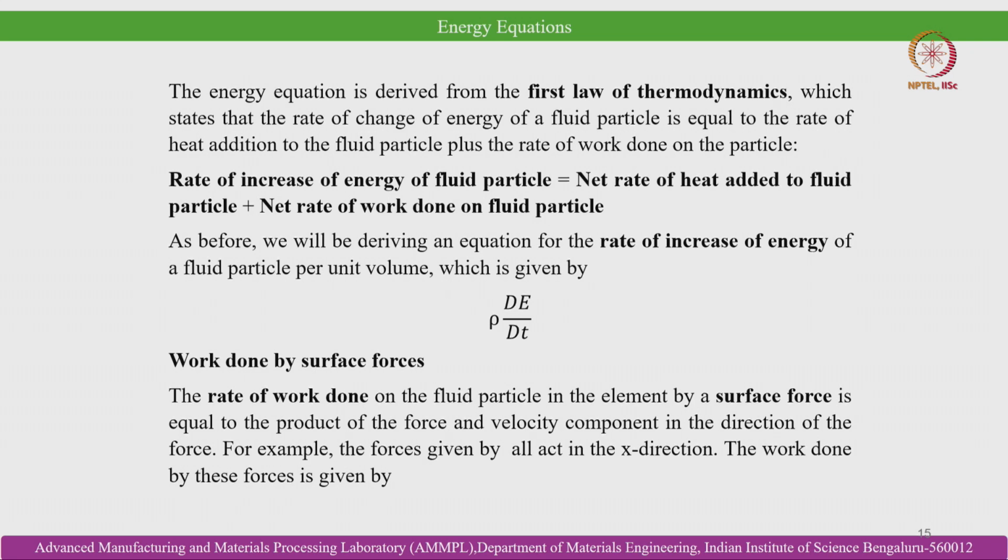As before, we will be deriving an equation for the rate of increase of energy of a fluid particle per unit volume, which is given by rho D/Dt, that is, rho times the substantial derivative of energy. Then, work done by surface forces. The rate of work done on the fluid particle in the element by a surface force is equal to the product of the force and the velocity component in the direction of the force. For example, the forces given here all act in the x direction.